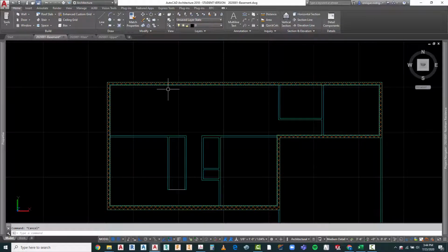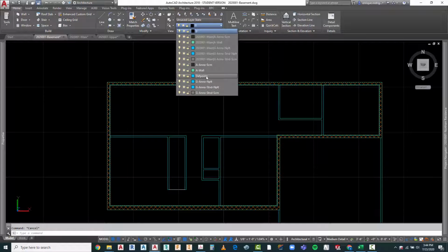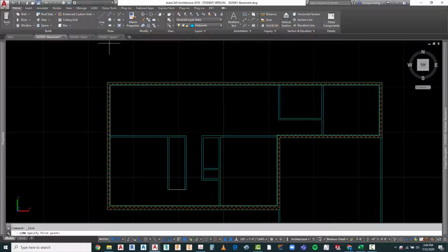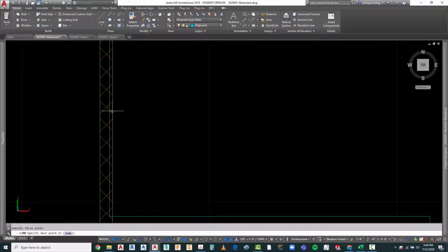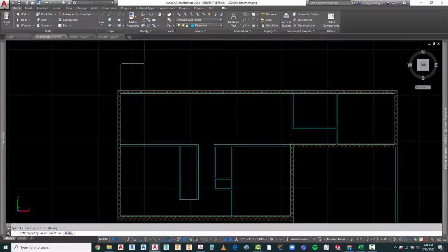So first thing I'm going to do is begin to draw the walls that will be supporting the fireplace up in here. Now our markups give me specific dimensions to do that. So the first thing I'm going to do is line those up. I am going to be in layer 0. Let's change that to depth points. And they're going to go from this 8-inch dimension here. And I'm going to copy this line.